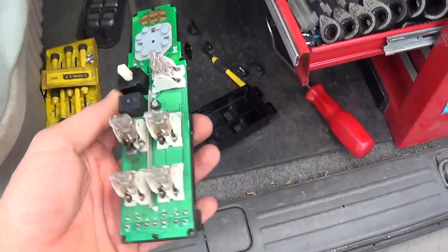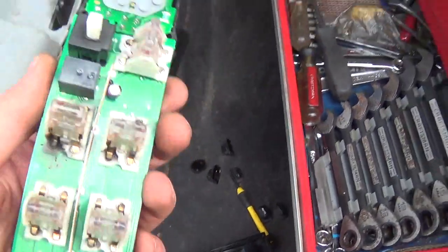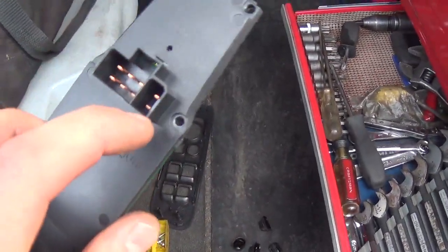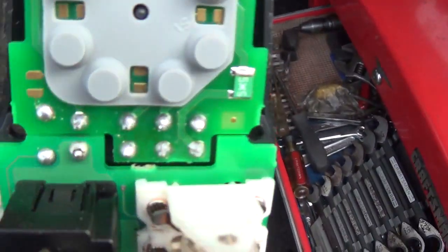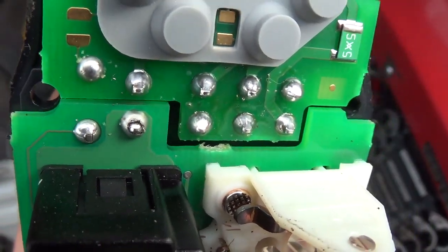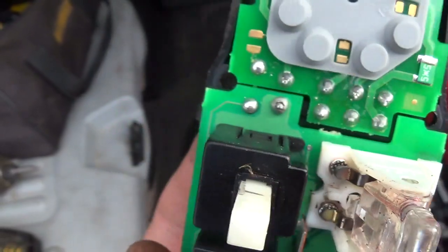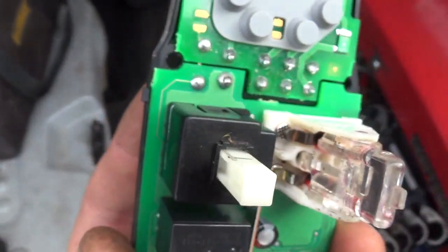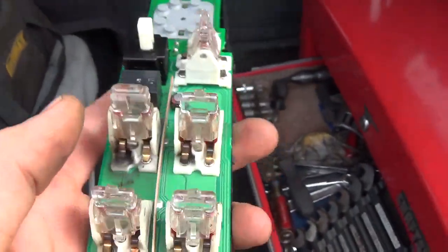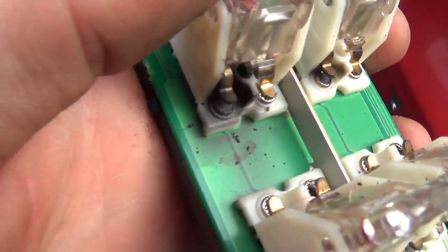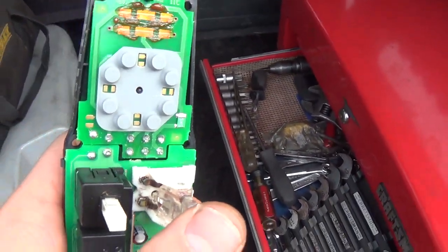Alright guys, for a complete 100% diagnosis, I couldn't help myself. I tore this thing apart. And what do we see? We're looking for that lower right pin right there. Come up here. Bingo. Cracked solder joint. Hardcore. And look at that thing. Wow. That's a confirmed problem right there. So, some of these contacts look a little burnt, but let's reflow the solder. It'll be good as new.